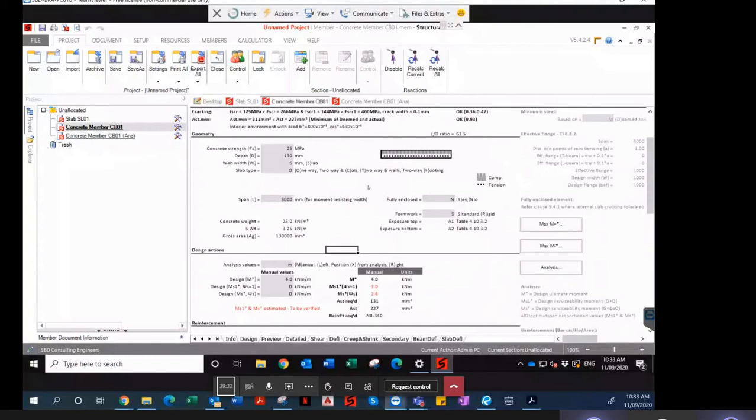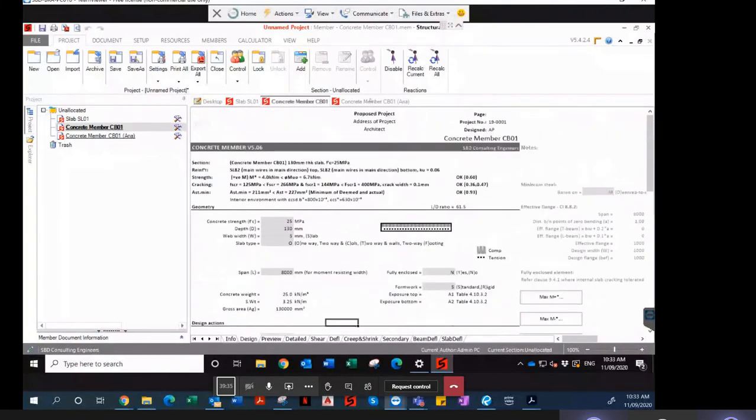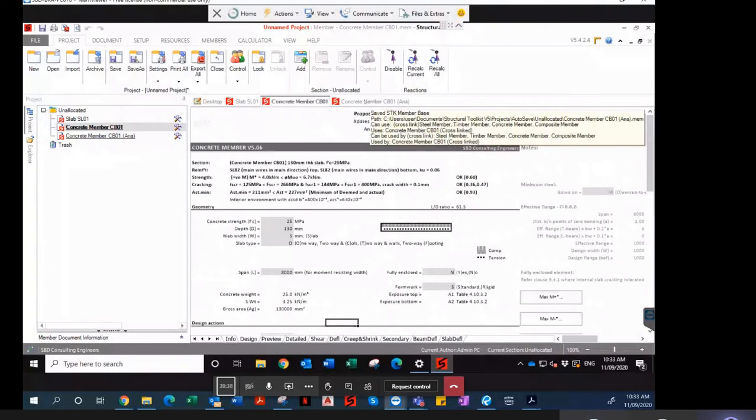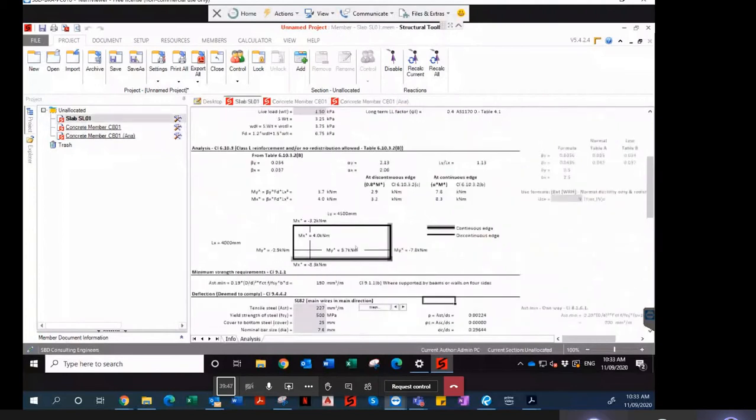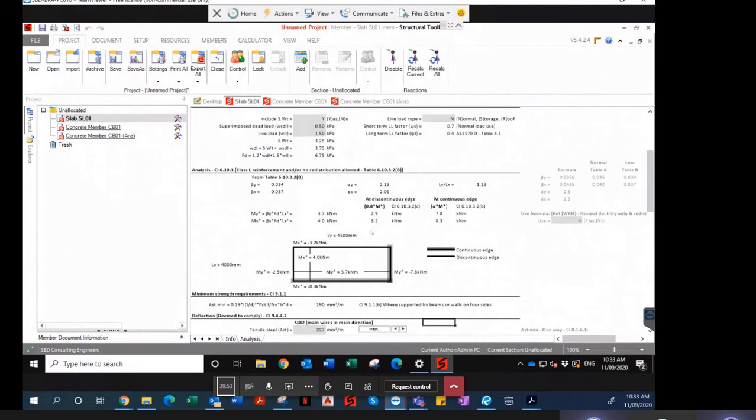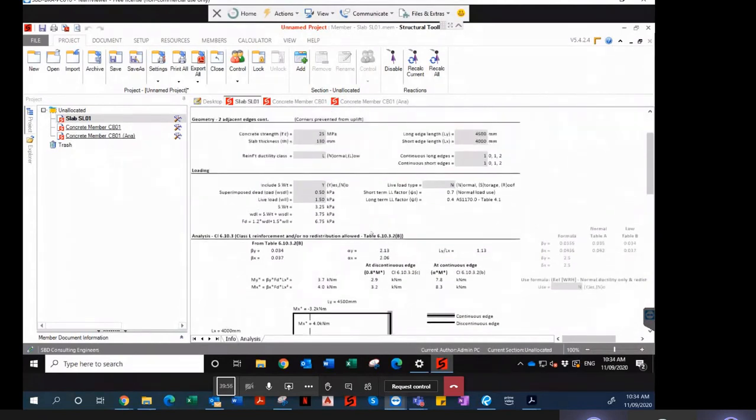What we can also do is, if we go to the analysis in here, sometimes we have point loads in the middle of the slab. So we've got dead and live point loads, and underneath those point loads we put a pad footing. So in a two-way slab, what we can also do is, if we've got a dead load of say 2 kilonewton, divided by 4.5 by 4, gives us a kPa value, isn't it?